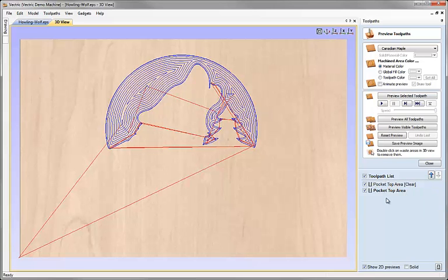If we hover the cursor over the name of that toolpath, we can see in the tooltip that pops up, that's the box there with the text in it, that it tells me the size of the tool and the parameters for that particular toolpath, and I can see there that that is the 1/2 inch end mill. If I come over the second one in the list, I can see that is the 1/4 inch end mill.